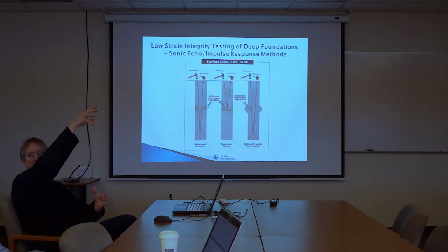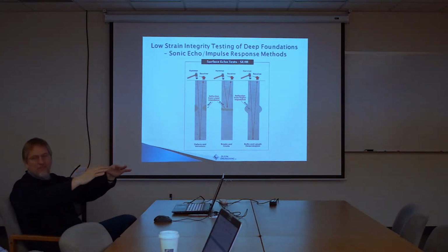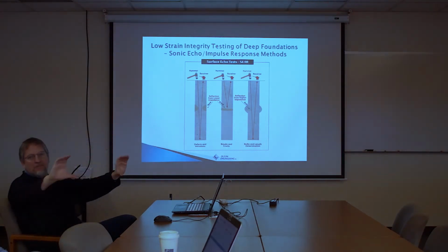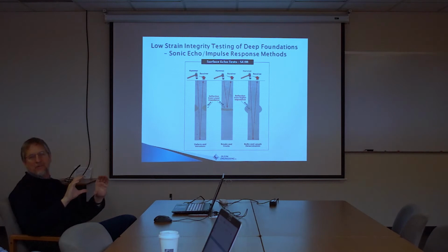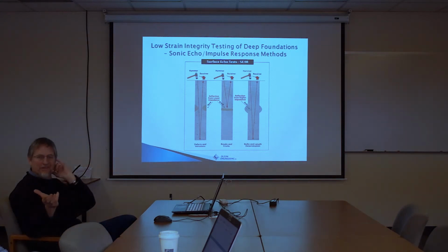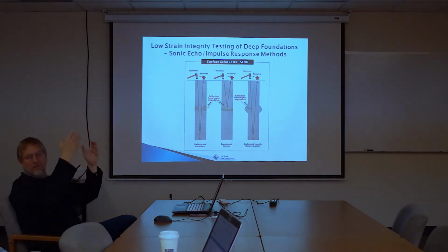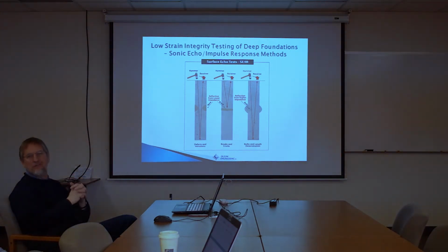If the tremie comes up out of the concrete, so it starts placing concrete down onto the shaft instead of up from below, then you've trapped that layer of bad material. It's a really common defect in a shaft for drillers that don't know what they're doing with slurry fluid. You know, if you ever have to pull the tremie out, you're almost screwed, almost always.